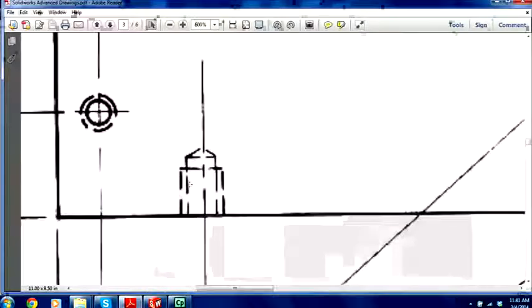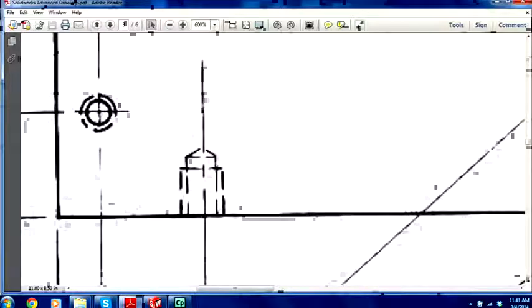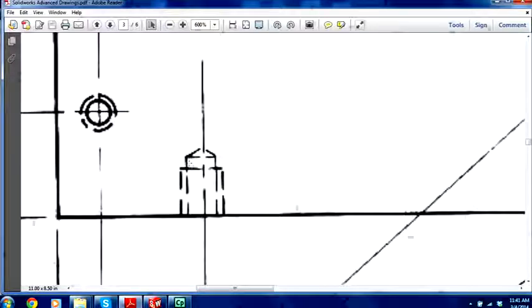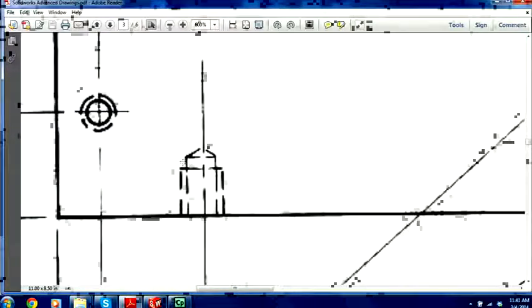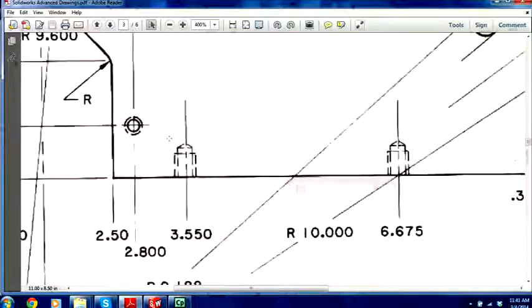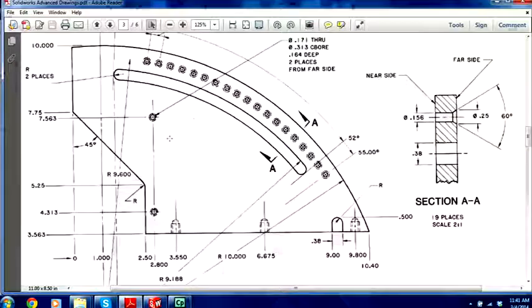Now let me just zoom into here. What does that look like to us? Basically, what's happening here is the person is drilling in with a drill. It's impossible to have a 100% tap. You're always going to have 25% just drill, and the 75% is the rest of the thread. You can file away the tap and use a bottoming tap and really extend that, but typically you're not going to get more than 75 to 90% of thread.